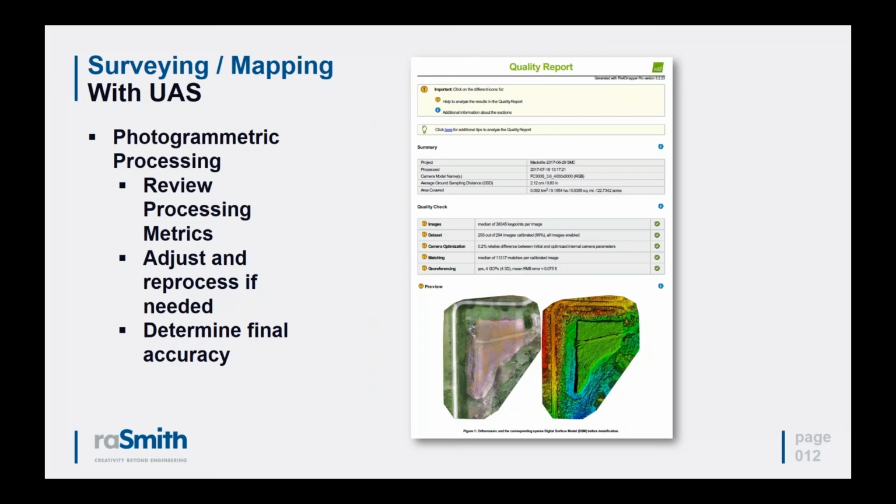And we subscribe to some methods that were created by the ASPRS, the American Society of Photogrammetry and Remote Sensing, and they have a set of standards that they use, including things like the 90th percentile confidence level, where you're checking multiple check shots, sometimes hundreds of check shots, that were collected with an instrument of greater accuracy, like a total station, for instance, and you're comparing those measurements to ones that were derived from the drone itself to give you a feel for what your accuracy actually is.